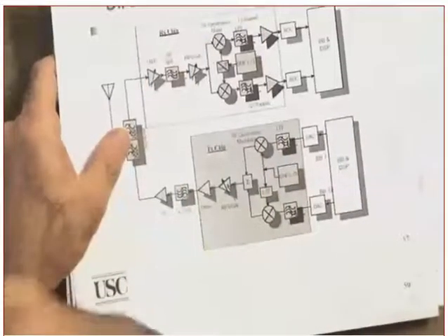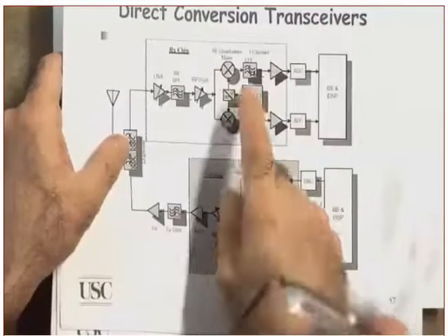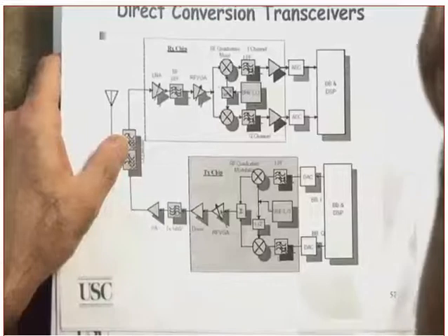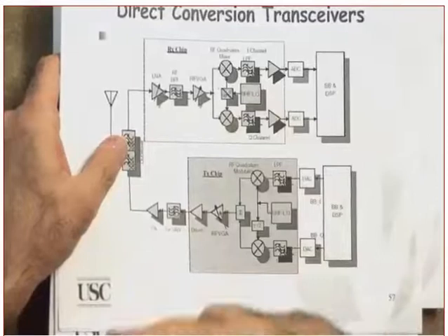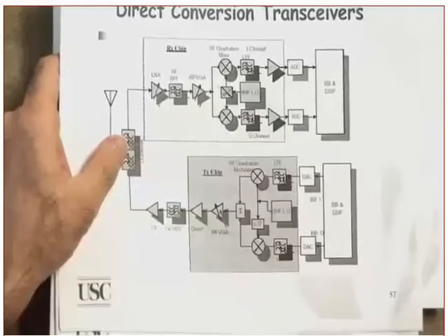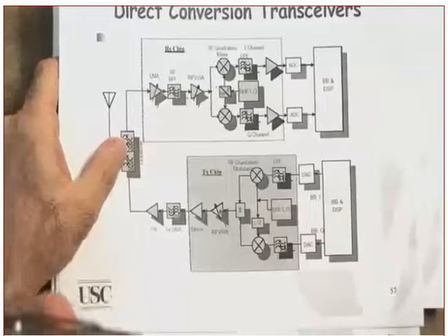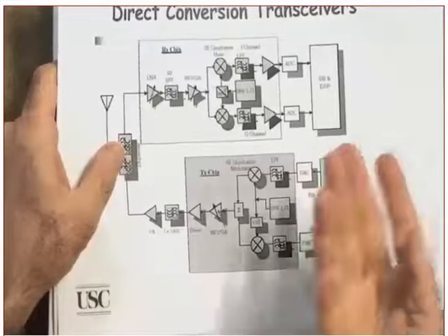We'll talk about it in detail when we get to the modulation. Are we using the same carrier? Which means we are not using two carrier frequencies. We are using one carrier frequency that supports double the rate, which means that you are improving the bandwidth efficiency. What is bandwidth efficiency? Units, bits per second per hertz. Yes?